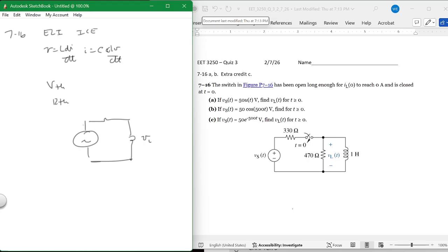Well, it would be the change in I with respect to T, right? Voltage across the inductor. And what did they give you? They give you the voltage over here is 50 e to the minus 500 t. So it's going to be some voltage, V Thevenin e to the minus 500 t, R Thevenin, and then over here, this is V over here.